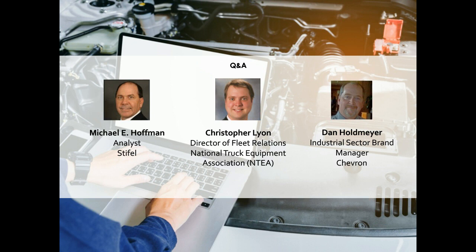And I don't know if the audience necessarily knows the ISO cleanliness code. As an example, it needs to be a 17, 15, 12, which refers to particle counts in the 4 micron, 6 micron, and 14 micron size particles. These are small particles that you cannot see, but they get wedged in between the valve spool and the valve body and cause erratic operation besides wear.